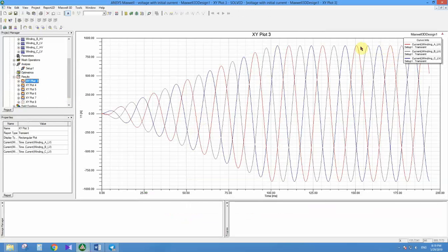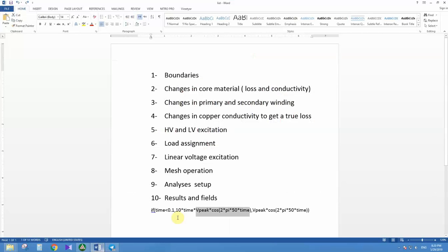The steady state voltage would be a cosine with the peak amplitude, okay? But when you multiply the ramp by it, it begins with little voltage and you don't see the inrush current, and you don't need to simulate lots of time to get to the steady state. It would start at the steady state. So I use this trick to make the simulation reach steady state much faster.